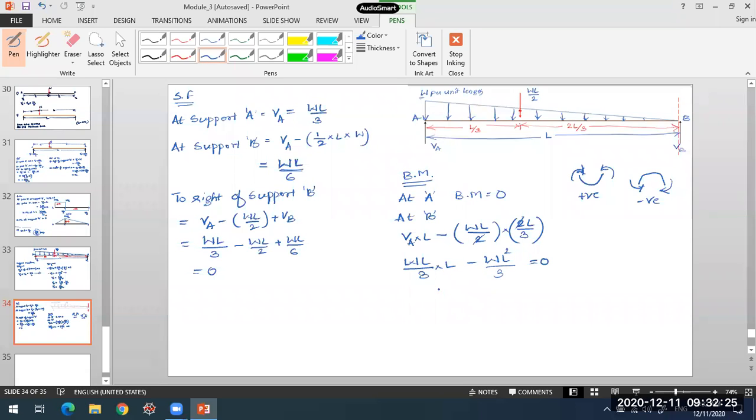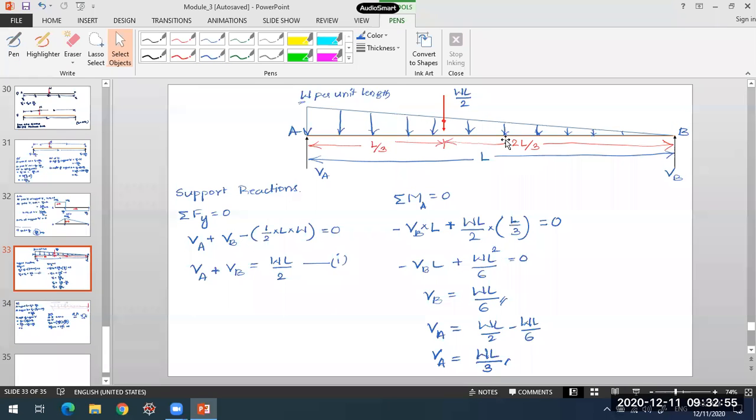But other than this, what I require is where the bending moment will be maximum because of this one load. We need to find where the bending moment is maximum. Clearly, I don't know where my shear force is changing sign. We had calculated the shear force, but I have not considered any point within the span of this beam, somewhere in the middle. I directly calculated the shear force at A and the shear force at B, and I have written the values over there.